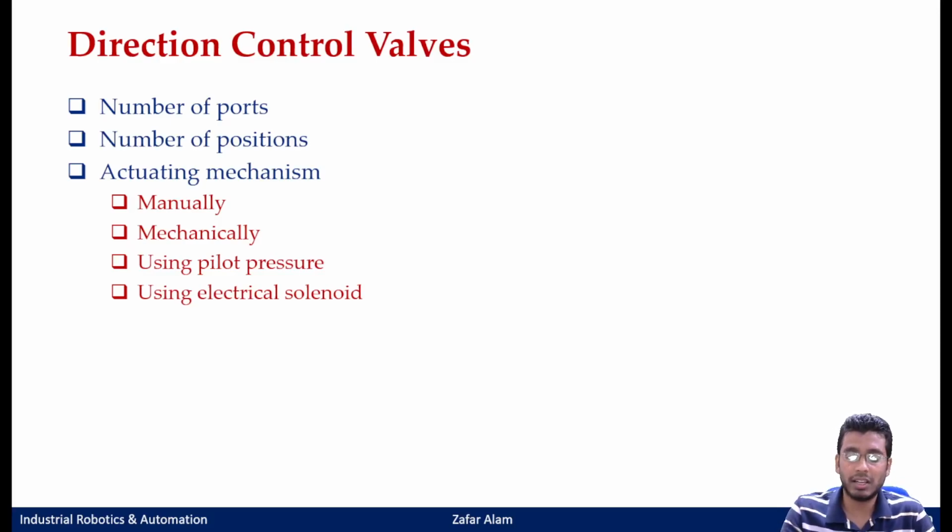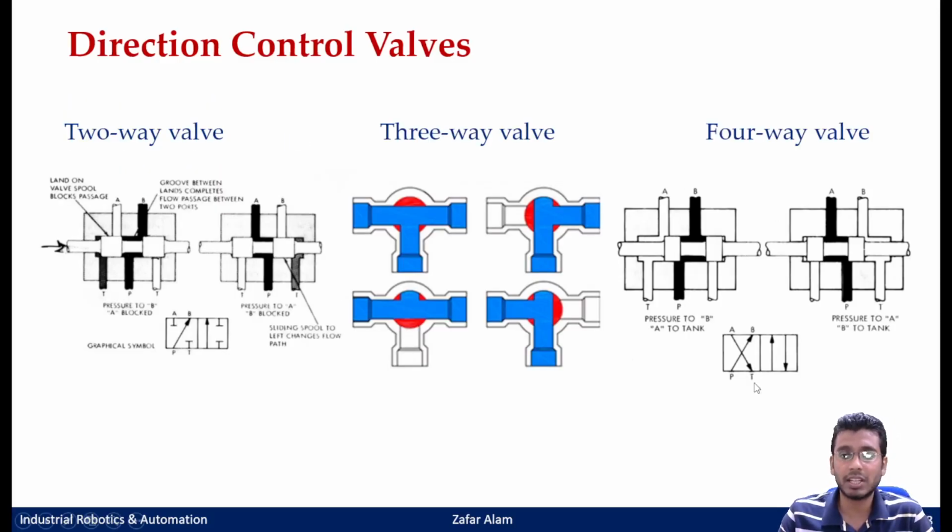If you can see in the previous pictures, these are only the valves that I showed you. These are the spools of the valves. Again, I have some cut sections, which I will be showing you. These are the positions in which these valves operate. For example, when these spools shift towards the left, then these positions will get engaged, and if it shifts towards the right, then of course these positions of the valve will get engaged.